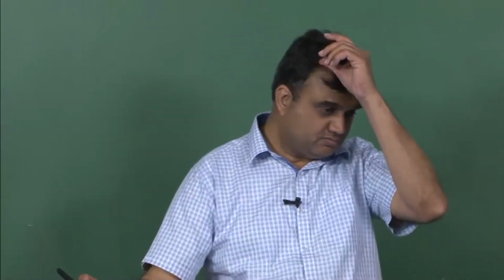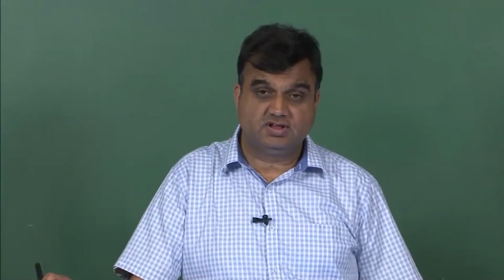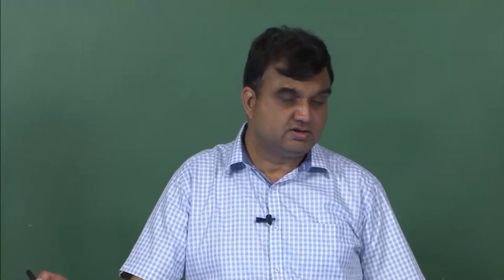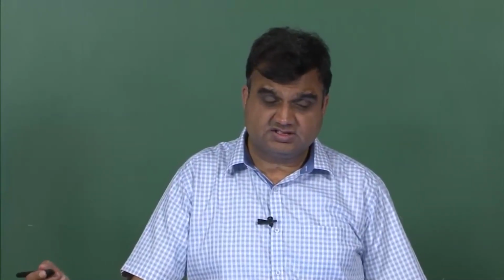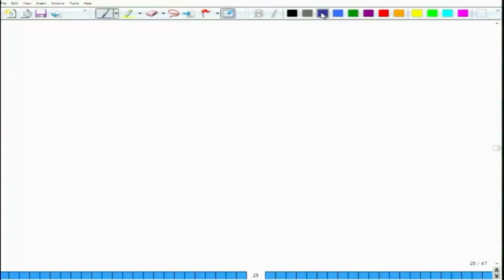These matrices are specifically named the extensional stiffness matrix, coupling stiffness matrix and bending stiffness matrix. Today we will talk about some standards in the context of how we define and specify the lamination sequence of a laminate. That is the language used across the whole industry by people who use composites in their designs. So, it is important to understand this standard laminate code, and we will spend some time on that.